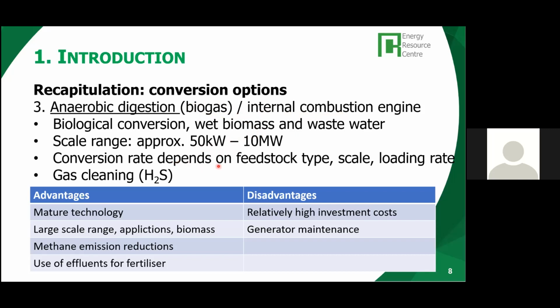The conversion rate very much depends on the type of feedstock, the system scale, and the loading rate of the system. And very critical here is also the gas cleaning of biogas, removing components that could cause damage to the combustion engine, particularly H2S.